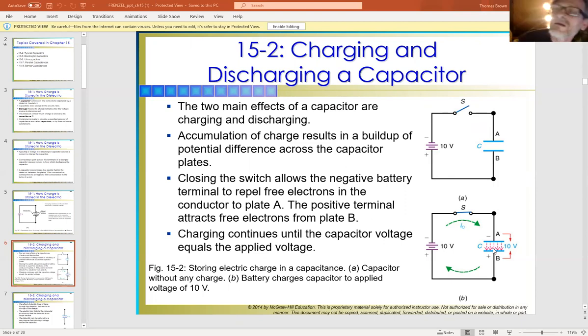It really depends on the capacitor and its rating, and we'll get into that and see how we can figure out what the time constant involved would be. Basically that would be based on our rating. So if I said you have a 10 microfarad capacitor, then we can juggle around with that and see how long it would actually take for that 10 volts to reach its maximum charge potential.